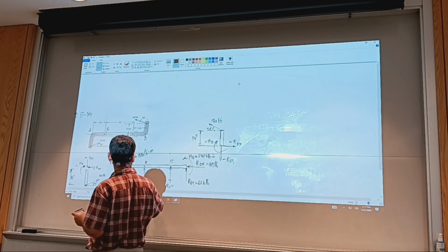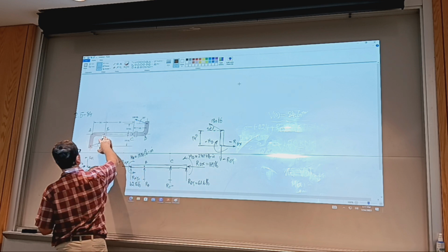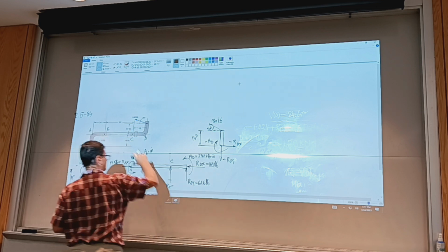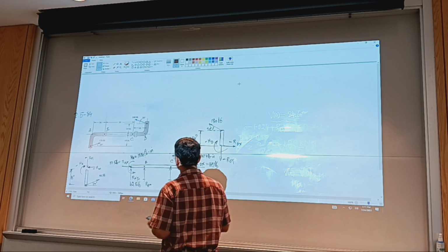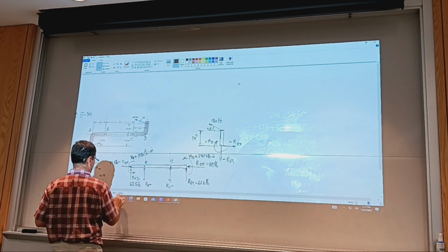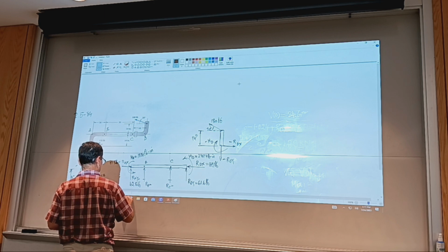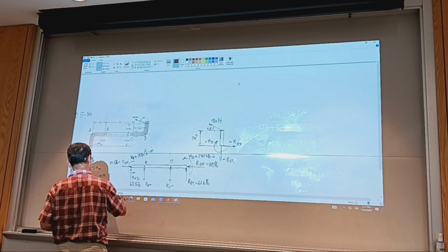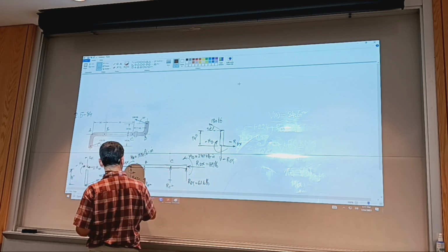So now we're good to calculate the reactions at the bearings. Again, there's a bearing here and a bearing here. This one takes the thrust. So let's see what their values are. I'm going to sum moments about point B, assuming positive to be counterclockwise, my choice, in order to calculate RC.